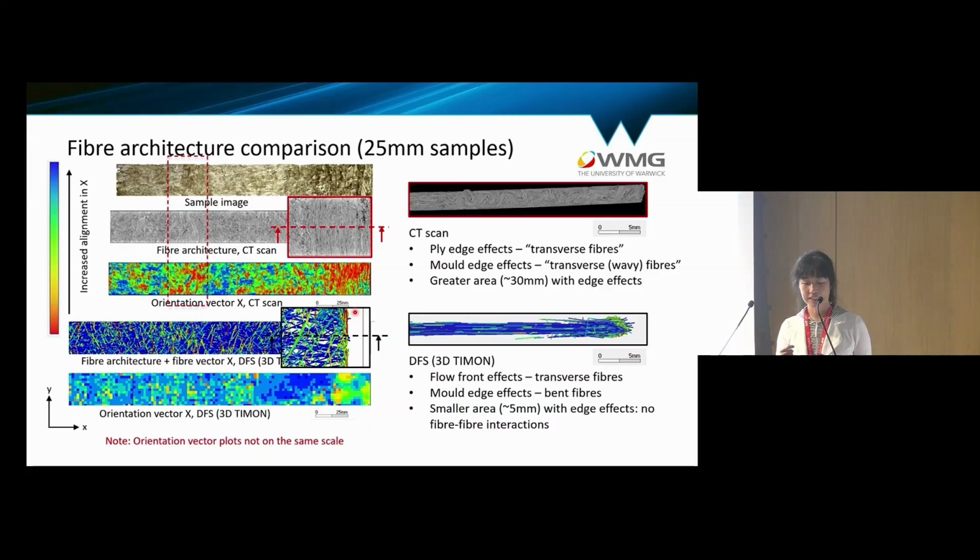Also, in reality, carbon fiber is not a material that can withstand very high compressive stress, so the material can buckle very easily. In the simulation, because it's modeled as a beam where the tensile modulus and the compressive modulus are equal, you get a much stiffer response from the carbon fibers. Therefore, you're not really seeing very wavy fibers, but instead just some slight bending in the fibers.